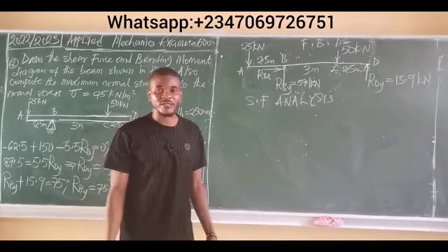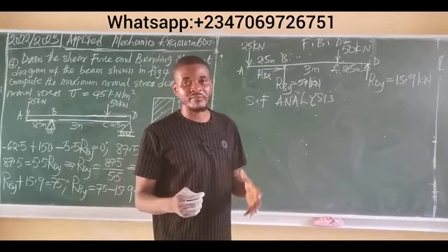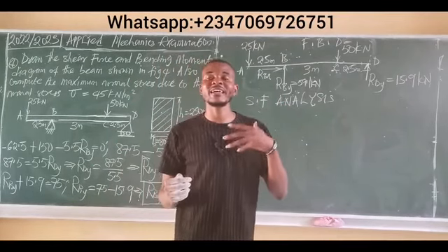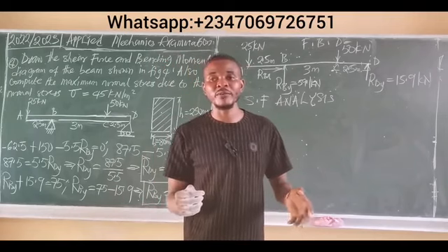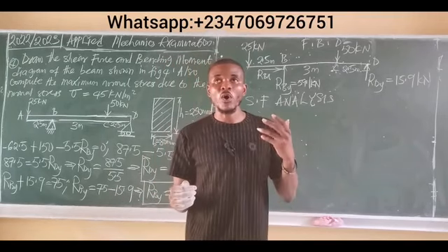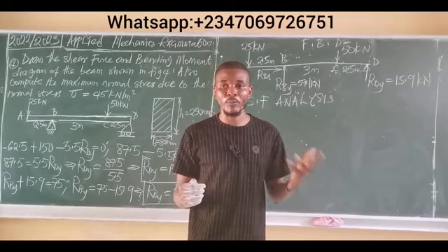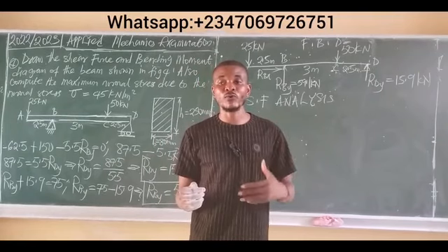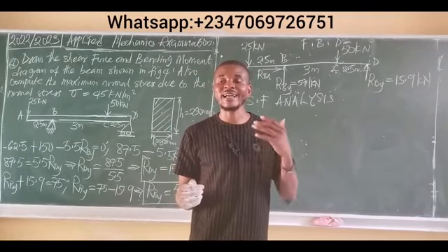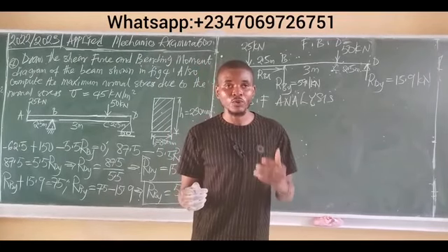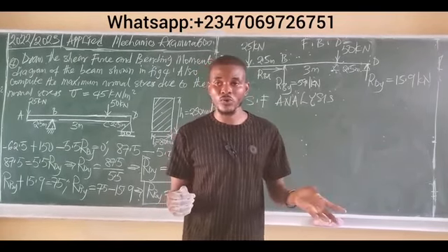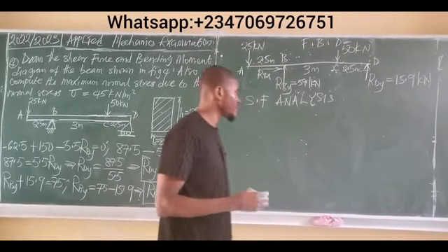Now, what is shear force? Shear force analysis simply means the stepwise summation of the entire force acting on the beam from the beginning of the beam to the end of the beam, considering vertically upward force to be positive and vertically downward force to be negative. And at the end of every shear force analysis, you must obtain 0 as the answer. So if you don't have 0 at the end, it means you're wrong somewhere. All right, let's start and see.